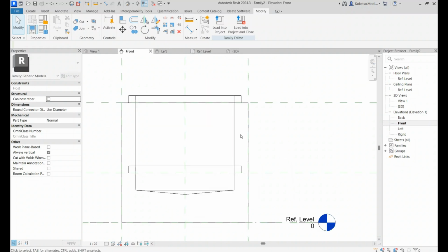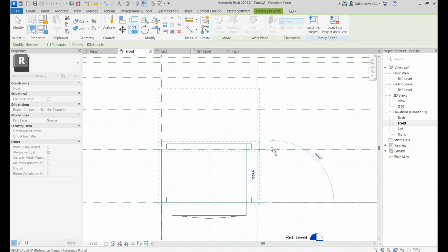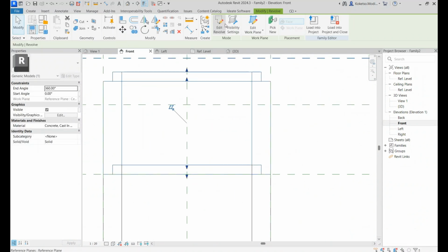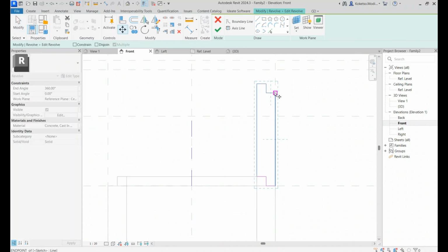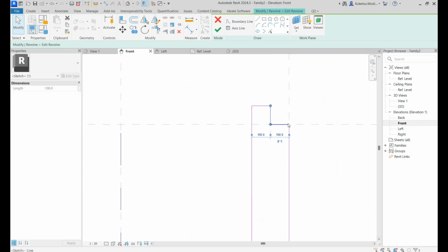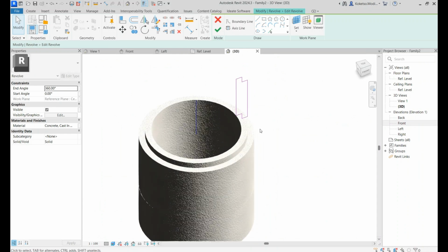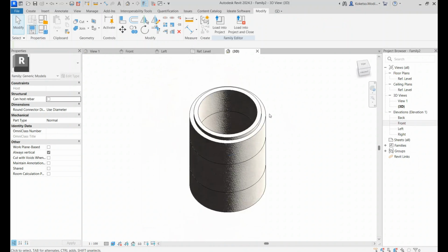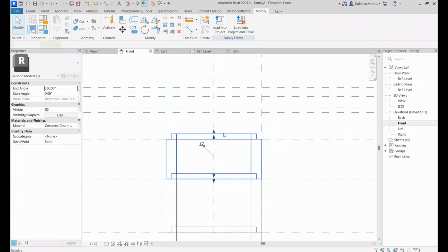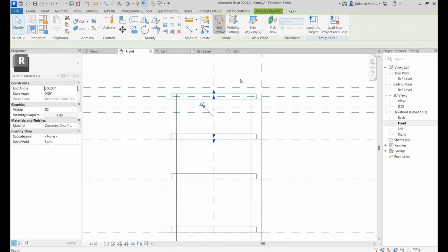So, okay, other than that, it's just a case of copying further up. So I'm just going to copy this one up, and I'm just going to say edit revolve. I'm going to select these lines only, and then I'm just going to reduce it, place it like that, make sure it's 100, make sure it's 100, and yeah, that's perfect. So if I go to the 3D view and say finish, this is how it looks. All right, the next thing is go back to the front elevation, select this, and then you're going to copy this one further, edit revolve.